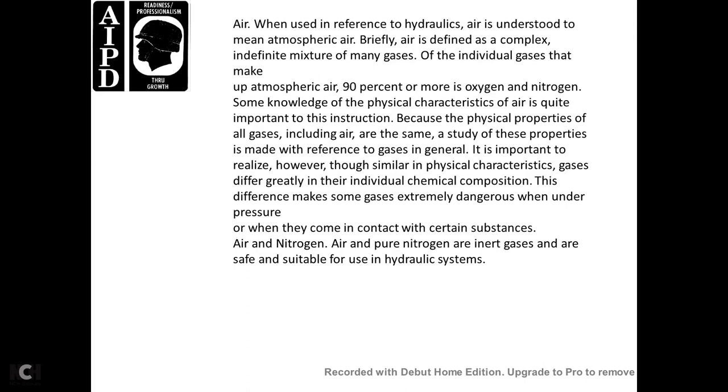At the same time, the study of these properties is made with reference to gases in general. It is important to realize, however, that while the physical characteristics of gases are similar, they differ greatly with individual chemical composition. This difference makes some gases extremely dangerous when under pressure and in contact with certain substances. Air and pure nitrogen are inert gases and are safe and suitable for use in the hydraulic system. Caution: only air and pure nitrogen authorized for use in Army aircraft hydraulic systems are to be used with the hydraulic equipment.